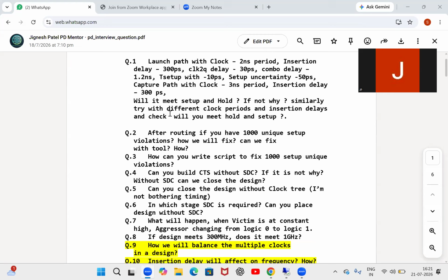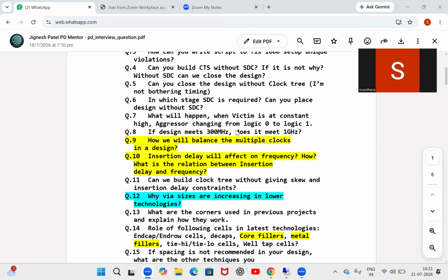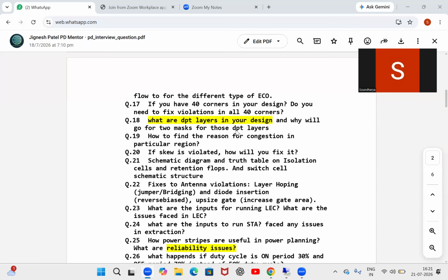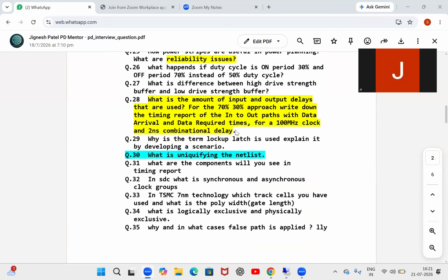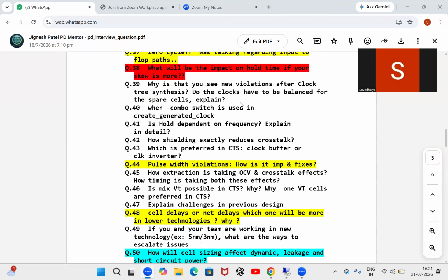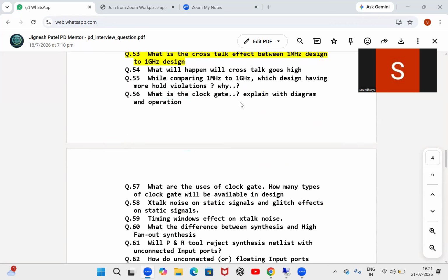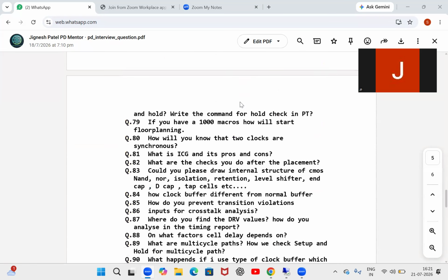You can mention that to make the automation, you can write one automated script using Tcl, just to check fan in up to 2, 3 levels of the macro. Can we do fan in and fan out for all those 1,000 macros also? That's what we can put into the script. We can run a for each loop, so for each macro it will automatically run and give 2, 3 levels of fan out. You can mention that this will give more detailed connectivity understanding.